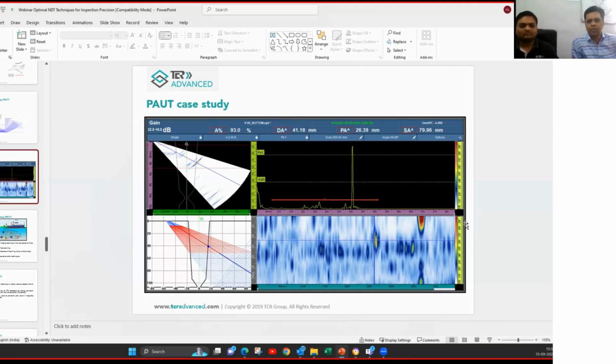Passive flaws are not detected, and that is the biggest advantage of acoustic emission testing. So that is another advantage. There are certain limitations for acoustic emission testing, and those are limited with respect to the skill set, the equipment which is used, the number of channels that we deploy, and certain interpretation part. Those are the high skill areas where we need good confidence in the system, from both ends: from the person who is interpreting and from the end user.